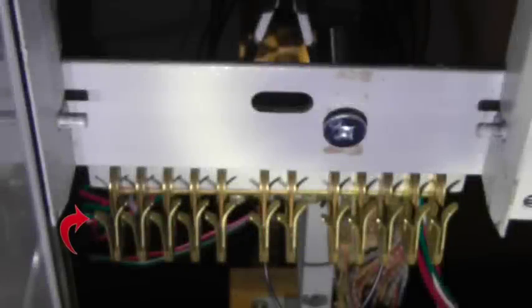Here are the 12 sets of jack springs that the plug prongs slide into. Nearly all the electrical connectivity between the connector and external circuits is handled through these jack springs. This includes DC power, ground, preceding circuit, ringing, and tone sources. The only exception is the connectivity to the called stations, which is handled by the wipers and bank assembly. This plug-and-play arrangement allows for easy removal and mounting of the connector switch.